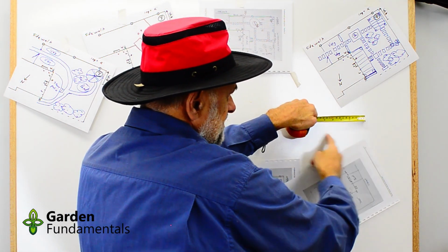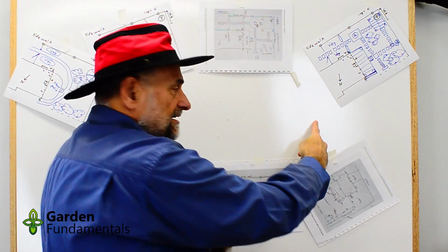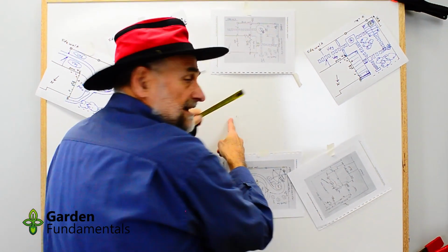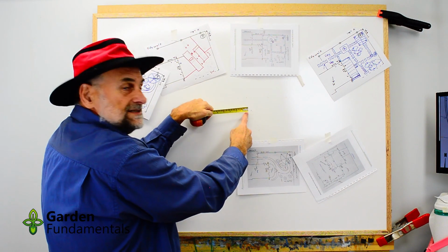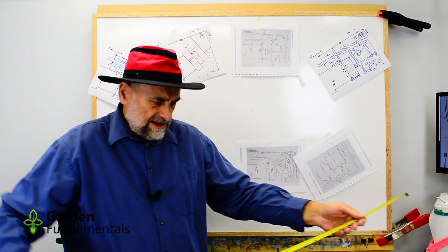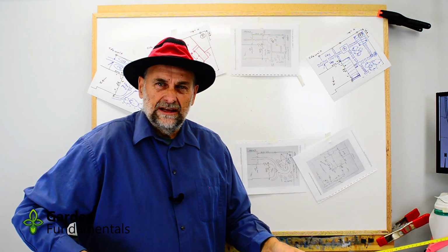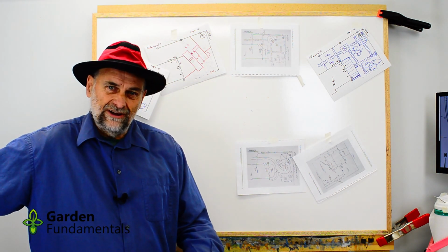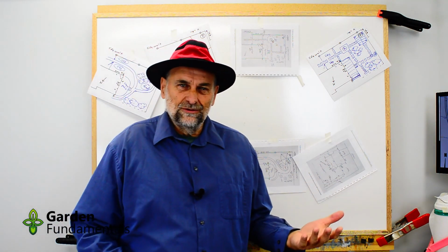Then you measure from there to there and you do it again. And again. And again. And then you measure the last little piece. And you just add it all up. In fact, when I'm doing this, what I do is I just take this, make it 10 feet long, and I just eyeball where I'm ending. And I just stare at that spot while I move over another 10 feet. Don't go out and buy a special ruler for this project.